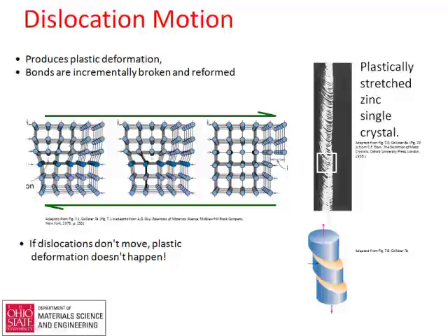These are all lined up along bonds, but there's this kind of dangling bond here. And what can happen if I put a shear stress on this, shear stress, talked about this before, is force over area. That'll tend to distort this. It'll tend to make this defect want to move this way, make it so that these atoms want to join with those atoms, and that could move this crystal defect off to that side. Okay, so if we put this shear stress on like this, it moves this defect, and it can cause the crystal to distort like that by moving the defect from this location to that location out to the end.